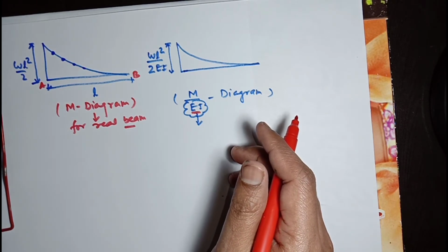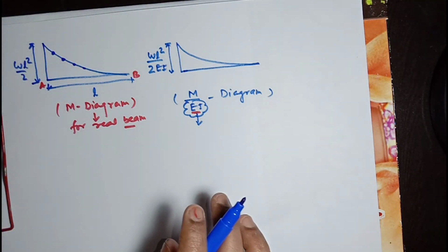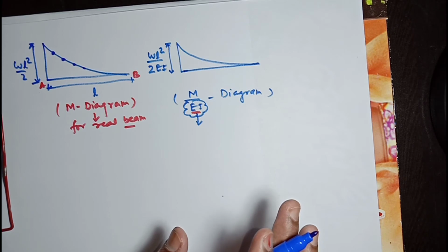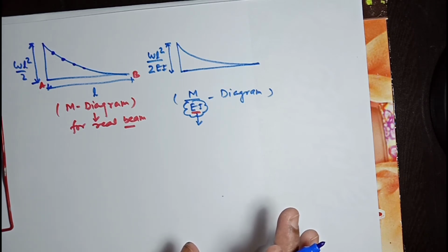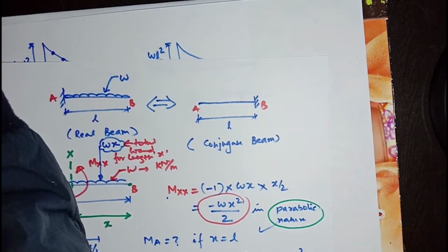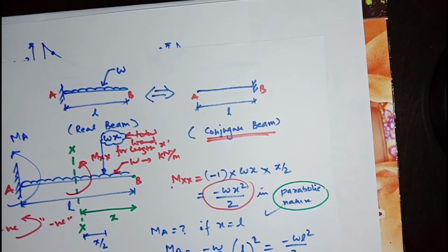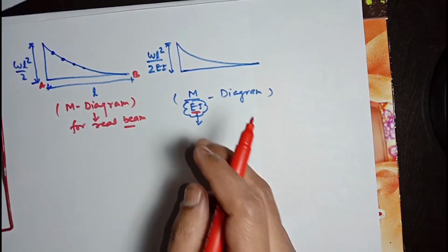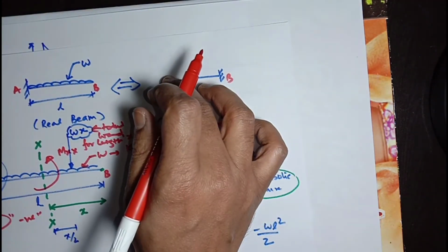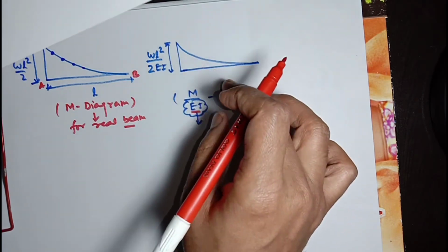Okay, fine. Now, as per the statement of deflection calculation using conjugate beam method, to develop a loading diagram in a conjugate beam, we need to put the M over EI diagram directly on this beam, the same as it is shown here.